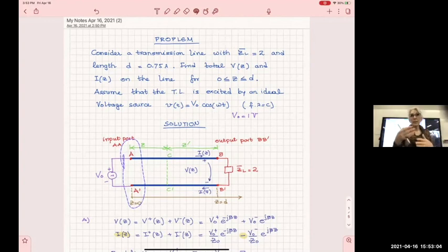Usually it's real plus imaginary, and that tells you it limits the source. So instead of being an ideal source where anything the transistor could produce comes through, it is not. A real source implies that only part of the power goes through. Maybe 10% of the power is going to go internally. If it's not a very good source, 20% of the power is going to be spent internally, and only 80% of the total would show up at the input port. That's what the internal impedance does. But it does not affect anything inside the transmission line.